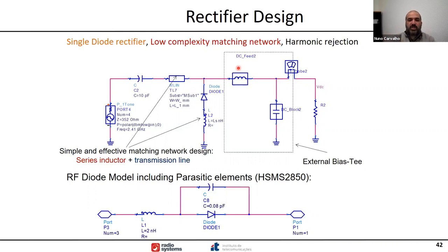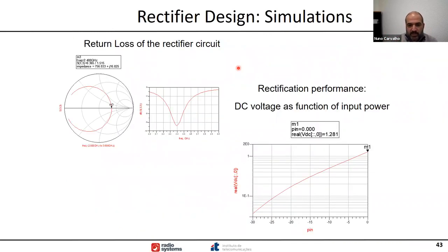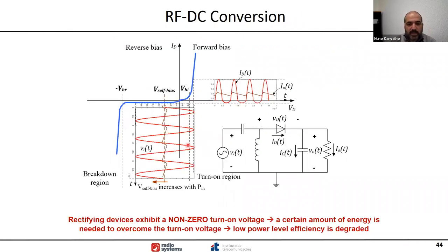So we can send these harmonics back to your diode to actually be converted again back into DC component. And this is something that we have been doing. So these are some of the examples of the scattering parameters that we did on the rectifier circuit and how we can implement that. And this, at the end, will give you the correct numbers of the capacitors, inductors, and resistors to design a correct RF to DC converter.